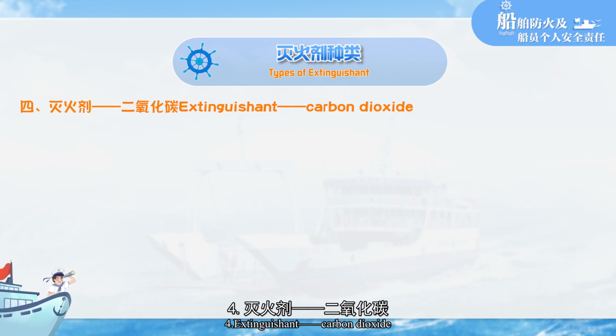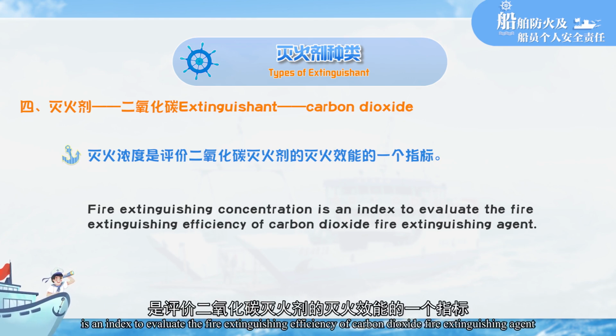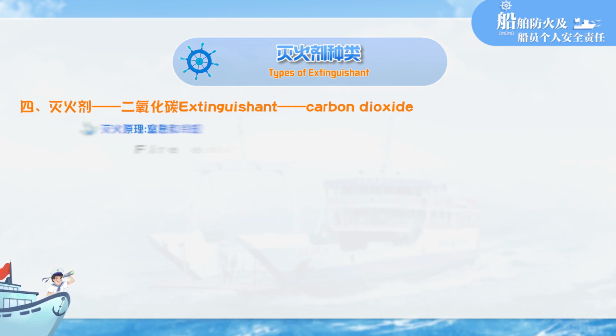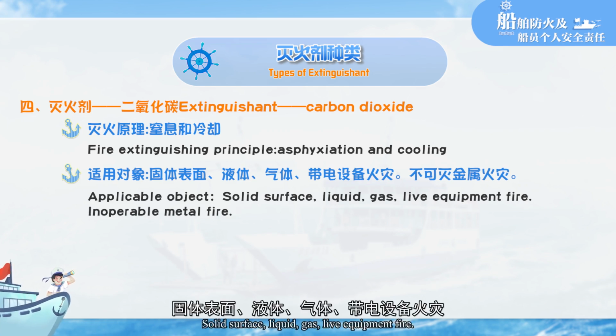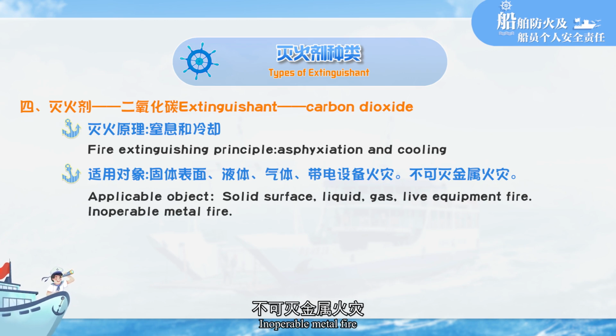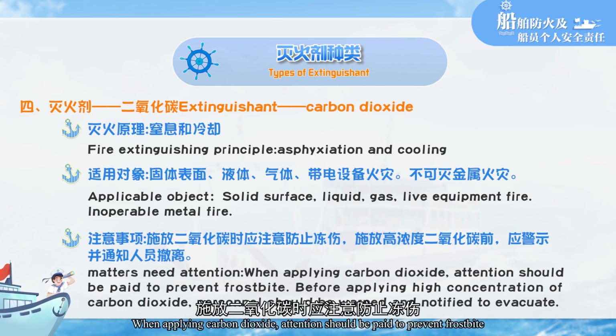Extinguishant: carbon dioxide. Fire extinguishing concentration is an index to evaluate the fire extinguishing efficiency of carbon dioxide. Fire extinguishing principle: asphyxiation and cooling. Applicable objects: solid surface, liquid, gas, lift equipment. Not applicable to metal fire.